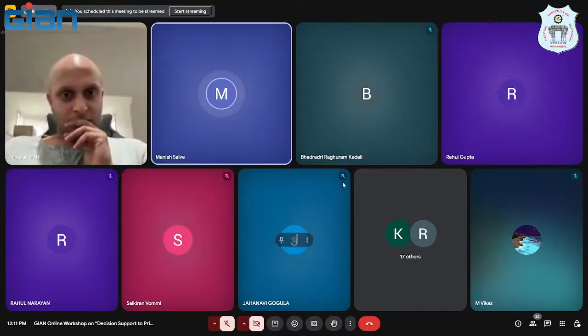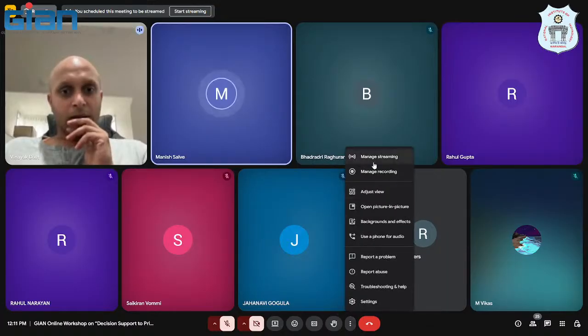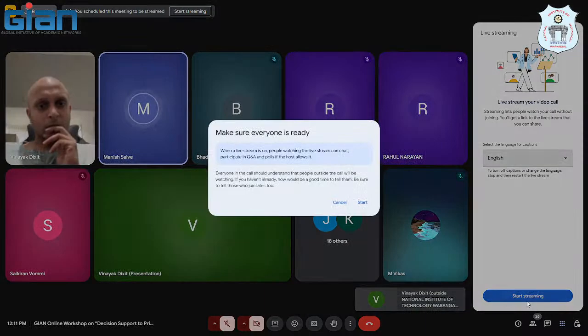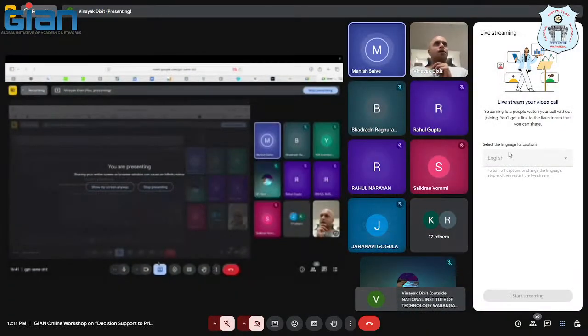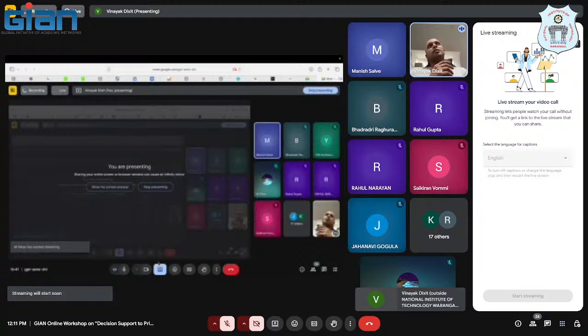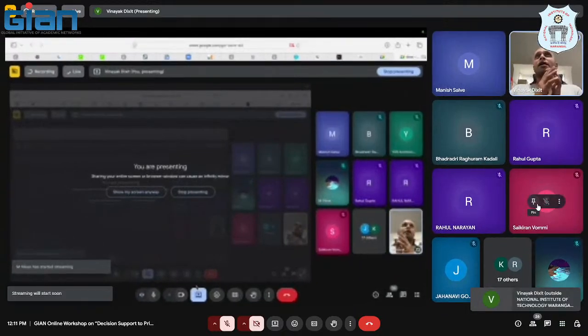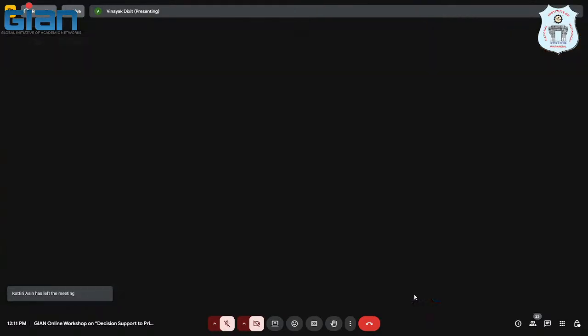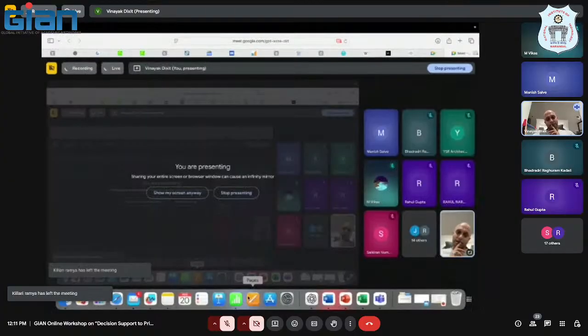Sir, I have one question regarding that simulation. You are mentioning the micro simulation and micro analytical simulation. What do you mean by micro analytical? Have you heard of Sidra and Synchro? They are called microanalytical because, when you do traffic signal synchronization, the delays are solvable.